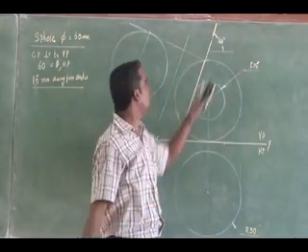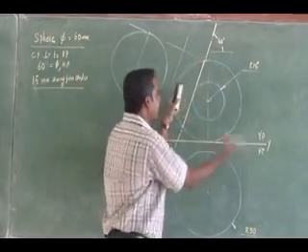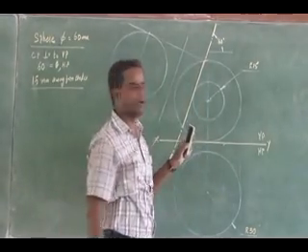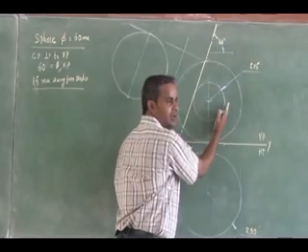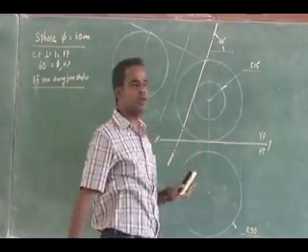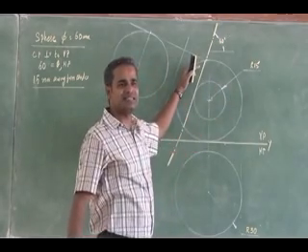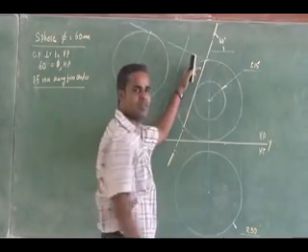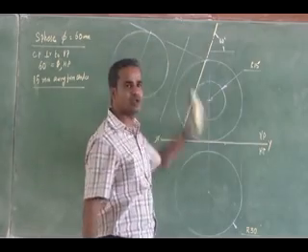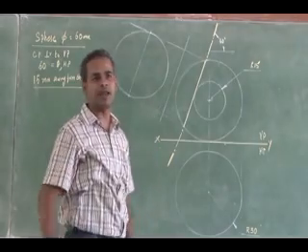To that 15 mm radius construction circle, I can tilt my drafter to 60 degrees, that is the inclination of the cutting plane, then draw the line tangent to that, such that a smaller portion is removed. You should not show your cutting plane here. So the larger portion will be retained. You move your cutting plane tangent to that inner construction circle, 15 mm away from the center, and you remove a smaller portion of the sphere. This is how you have to represent your cutting plane.